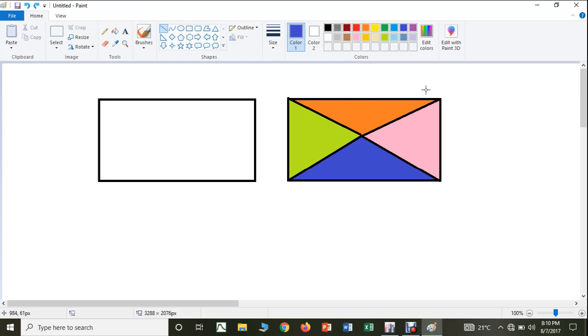so you will get a UDL that you can apply on this beam. Similarly, you calculate this area and convert it from kilonewton per meter square into kilonewton per meter, so that will be the load that this beam will receive. Similarly, you convert the area, and that will give you the load that this beam receives. And you convert the area, and that gives the load that this beam receives.